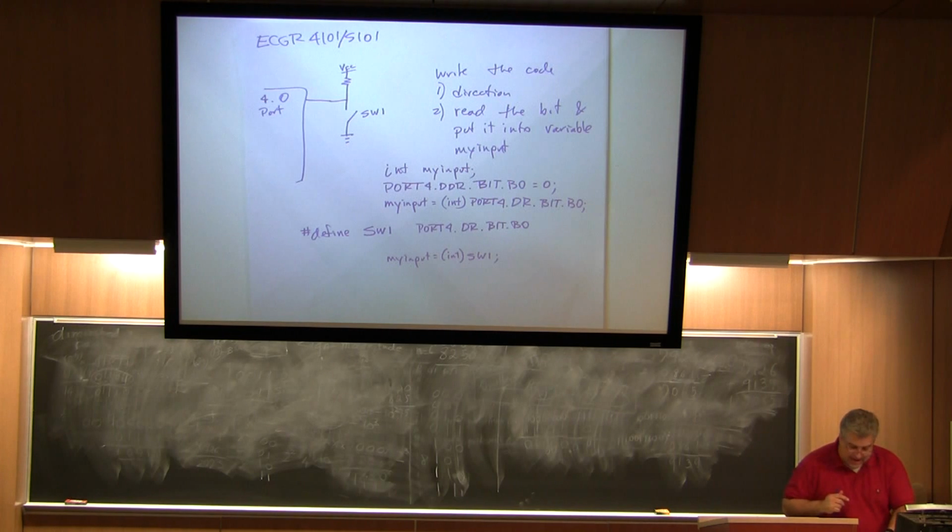Now, let's say I had a little bit of code that I wanted to do, and I'll add some more things. Let's say I want to turn on the LED and turn off the LED at some time. So maybe I'll do a pound define LED on 1, right?